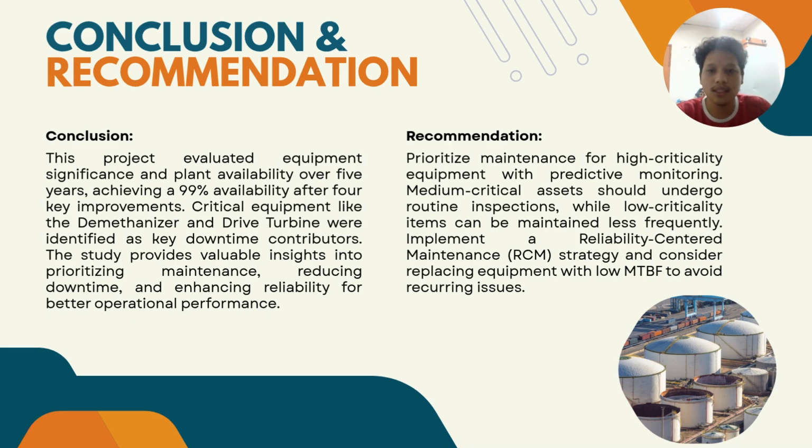For recommendations, prioritizing equipment based on its criticality is key. High critical equipment requires predictive maintenance and enhanced monitoring, while medium critical assets should undergo regular inspection. Implementing reliability-centered maintenance (RCM) and upgrading low MTBF machinery can further improve system reliability and reduce recurring failures.